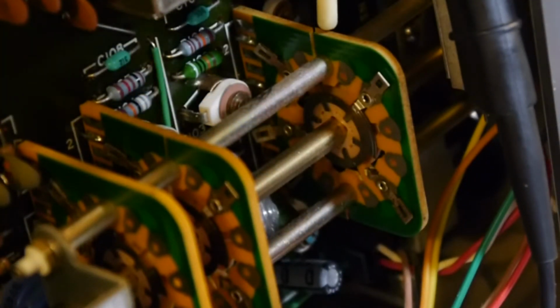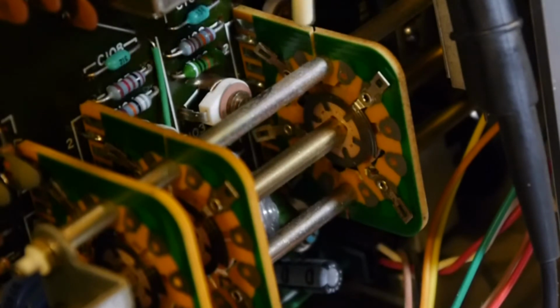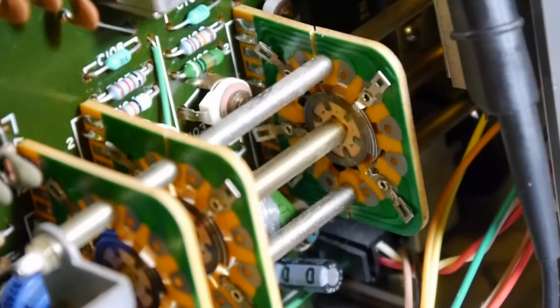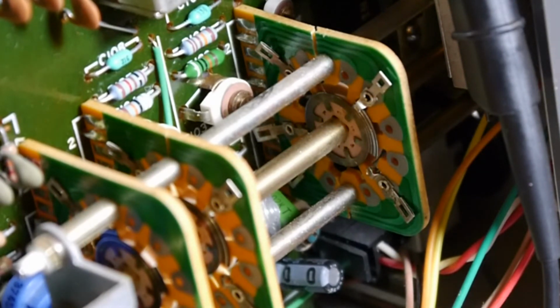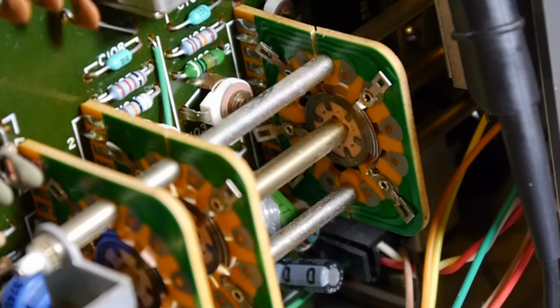There's your problem there. The chap wasn't lying to me, was he? I think he said the switch was broken, and I should have taken him at his word. The PCB board that the switch is made up of is broken in half there, and that one is also broken in half. I can see a crack running clean through the traces, and I'm trying to work out if the switch looks pushed back. I don't think it does, but yeah, there's the problem.